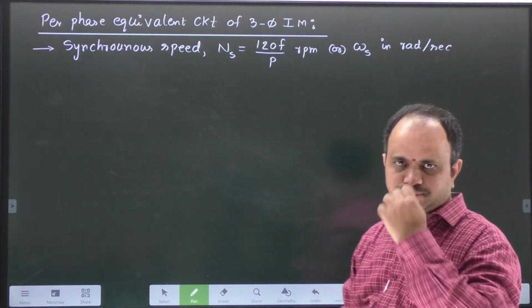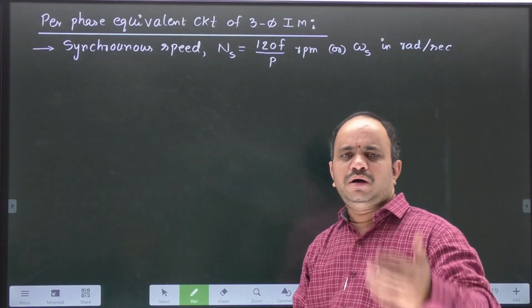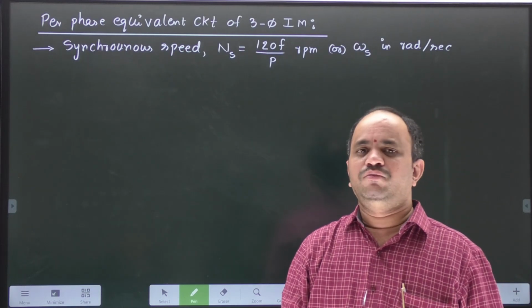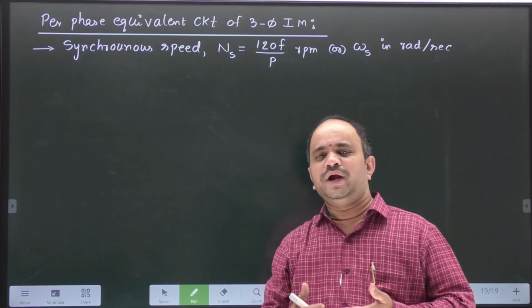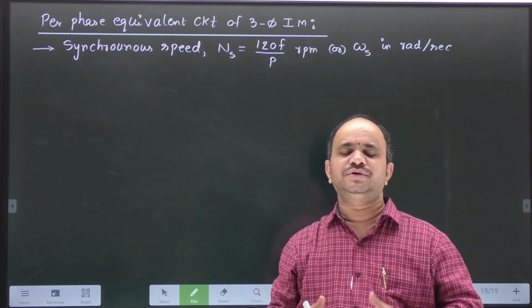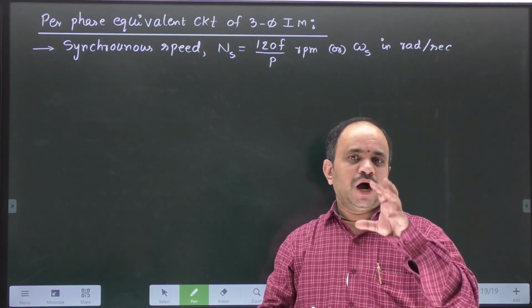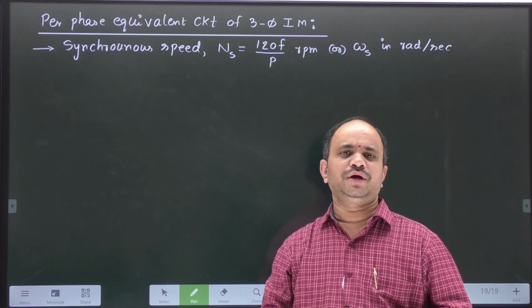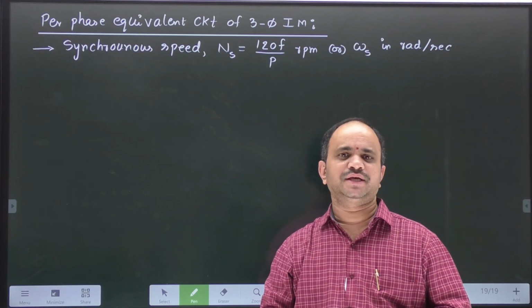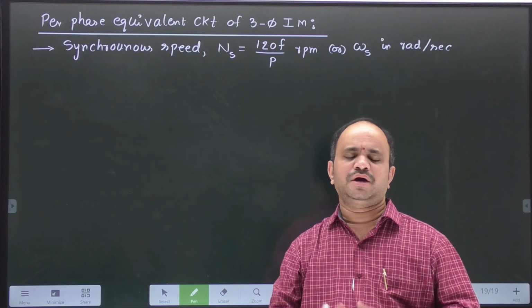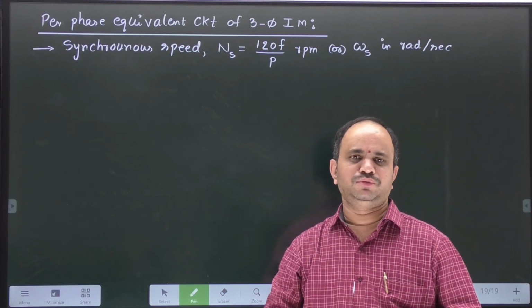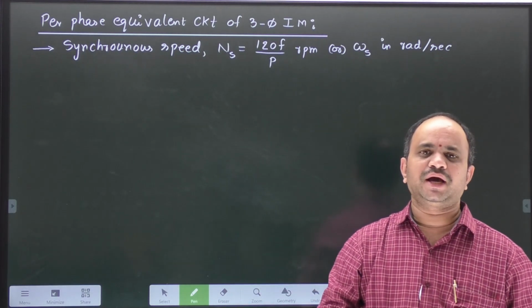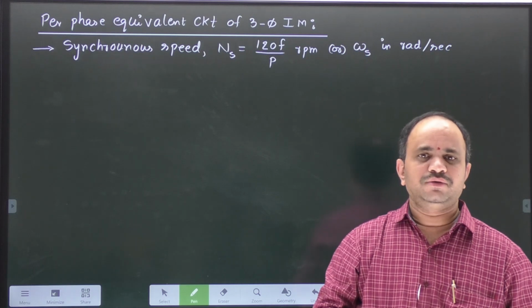second. Okay. Now when this rotor air gap field cuts the rotor windings, okay, then what happens? When the rotor winding has a closed path, some currents will start flowing in it. How the rotor winding will have a closed path? It can be short circuited by using end rings in the squirrel cage construction, and it can be closed through slip rings in slip ring induction motor. Okay, so due to the interaction between air gap field and the rotor currents, an electromagnetic torque will produce.